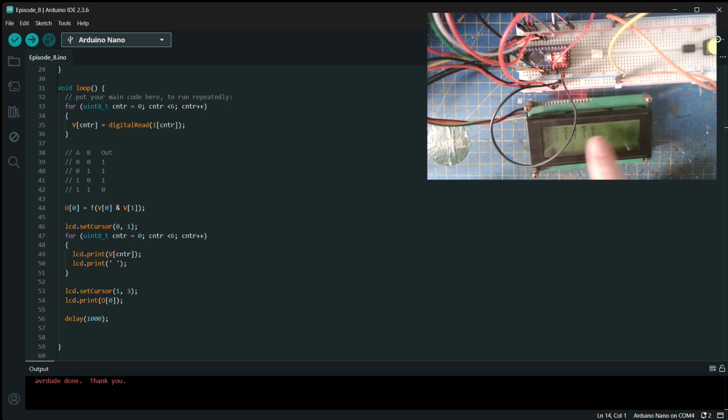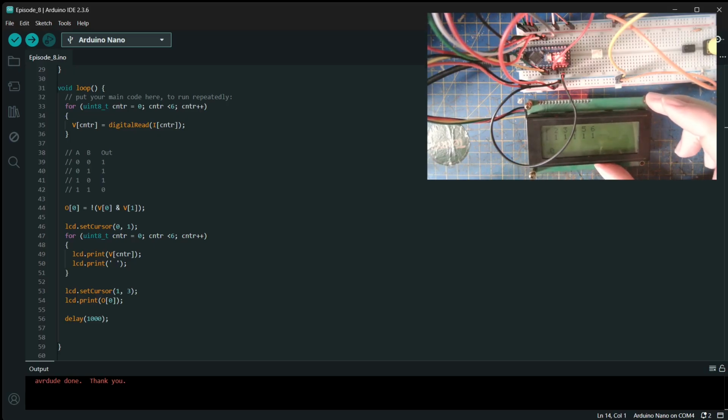You can have a row of, say, 10 points with a 0 or a 1, so you can see which state the points are in. Or do the same sort of thing with signals or block occupancy sidings. It's a nice little window into what the microcontroller is doing, either to give you some information that you might need or to give you some sort of debugging information.